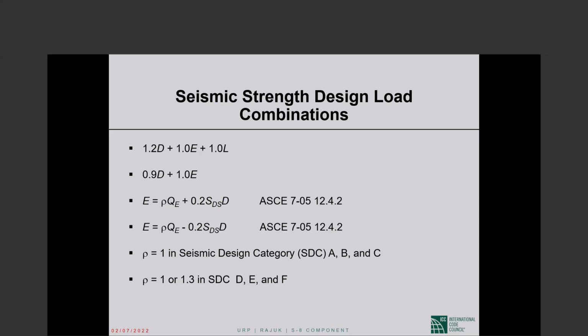Okay. In BNBC 2020, there is no rho. The subject of redundancy is mentioned in one paragraph, but there is no redundancy factor in BNBC 2020. And this is one of many major topics that are simply not covered. Okay, and I will devote one lecture to those things.